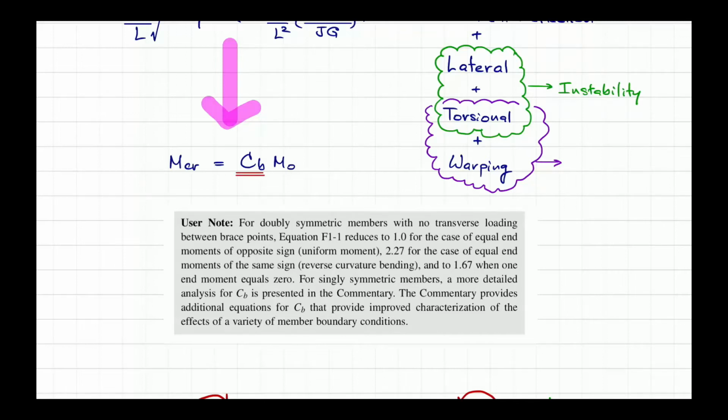So you construct the flange, you construct the web, assemble them into a wide flange cross section, and then you have the discretization in all three dimensions. So along the axis and along the X and the Y in the given cross section.